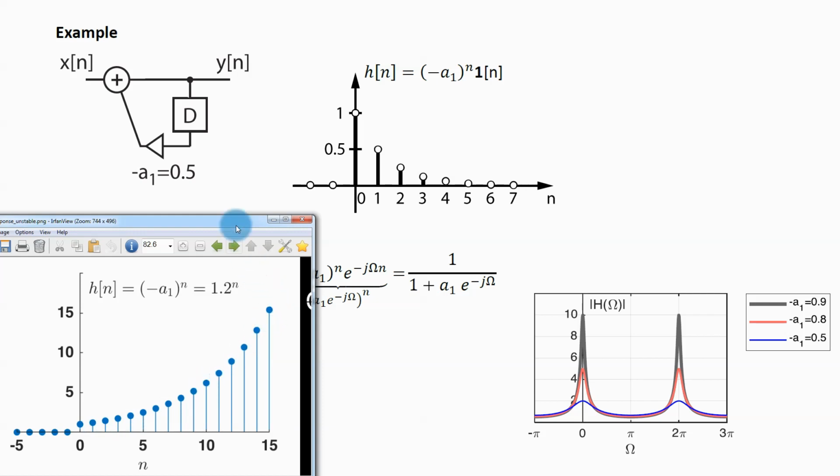You can see the problem even in this schematic. If this coefficient is greater than 1, then the value circulating in this filter is getting bigger and bigger after each clock cycle. If this coefficient is greater than 1 and you feed such filter any non-zero signal, its output will likely diverge to some infinity and the filtering will not work. We say that in this case the filter is unstable. And this is the drawback of IIR filters.